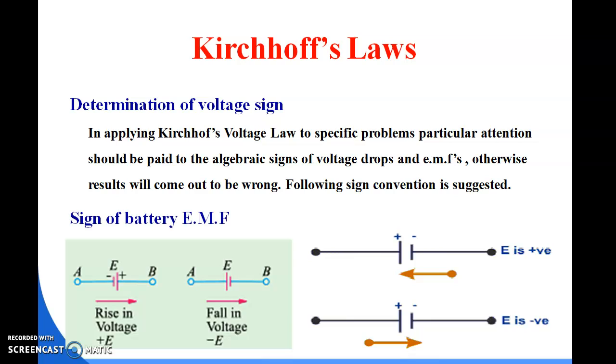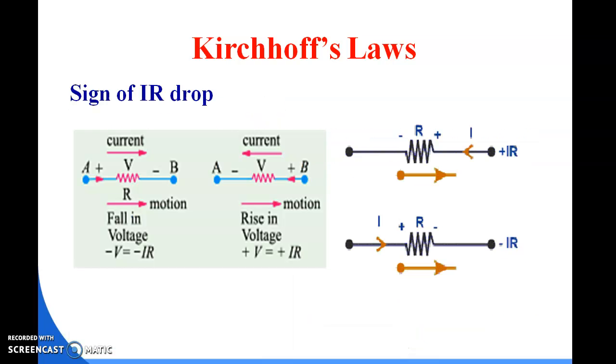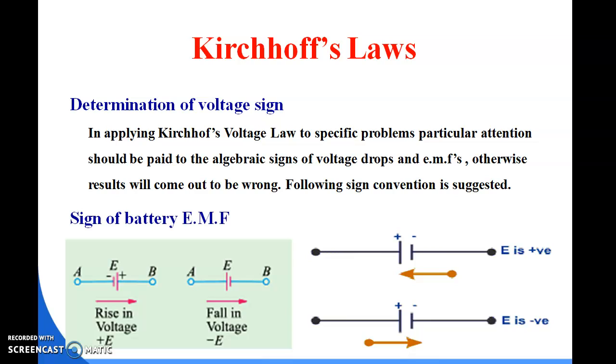Then we will determine the voltage sign. In applying Kirchhoff's voltage law to specific problems, here we will pay attention to the algebraic signs of voltage drop and the EMF. EMF means electromotive force. Otherwise the result will come out wrong. So first we will learn the sign convention. The sign of battery EMF is